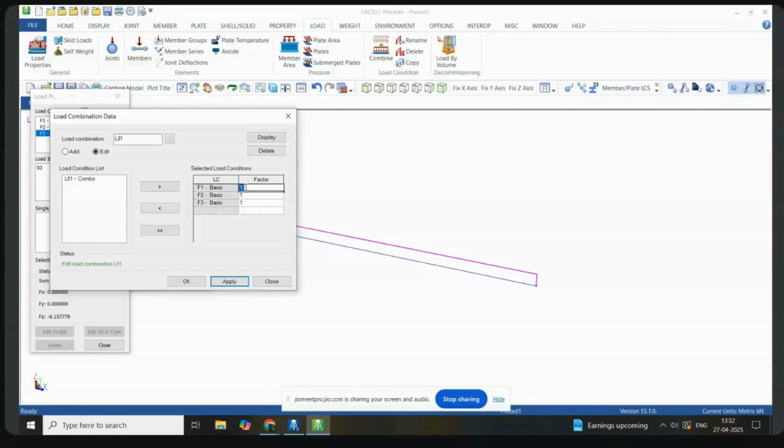Something like weight growth factor. Weight growth factor is this: when we design a structure and reach the final stage, there is a high chance that the weight may change because we go through different iterations. After each iteration, it can come down or go up. So for safety, when we start a design, we will consider 20% extra weight. That is the FEED stage.